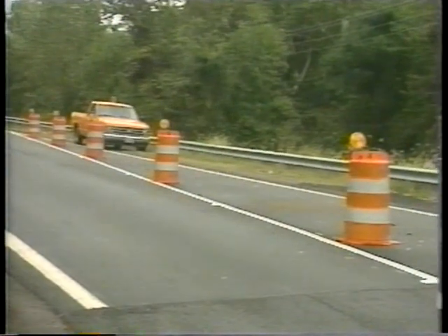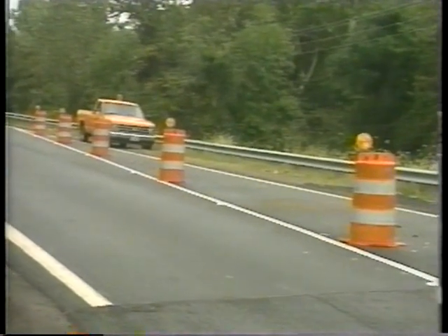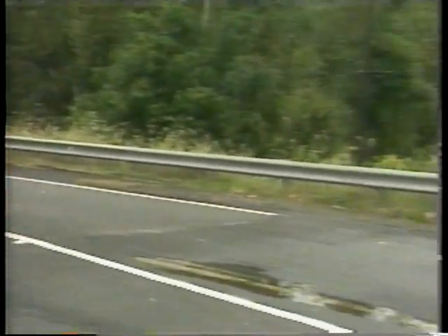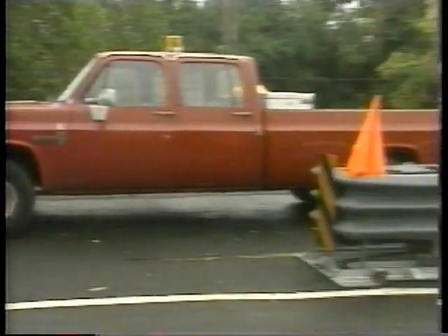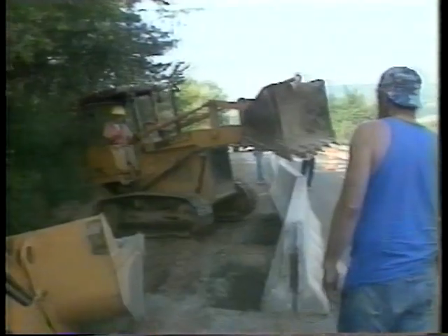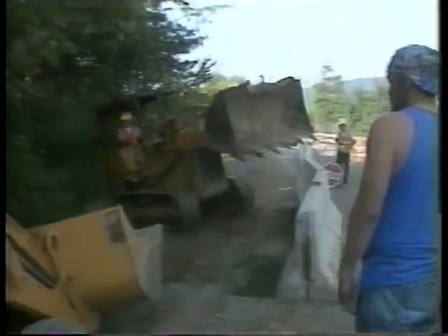Avoiding introducing severely restricted travel paths in the approach to the work areas or within the work area. Using lightweight, less hazardous channelizing devices and crash cushions on barrier ends. Planning so there are no conflicts with traffic and workers and equipment.